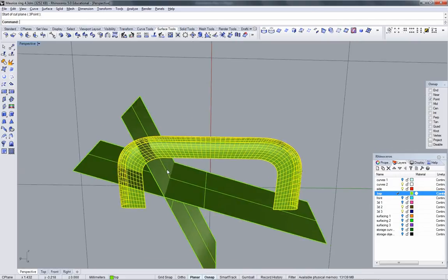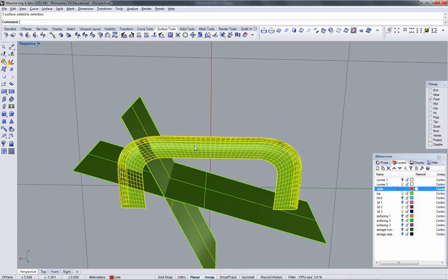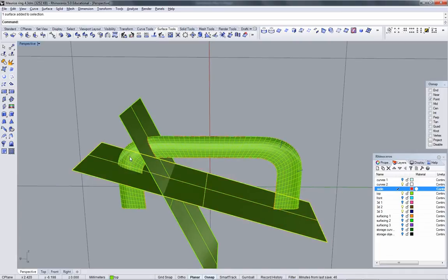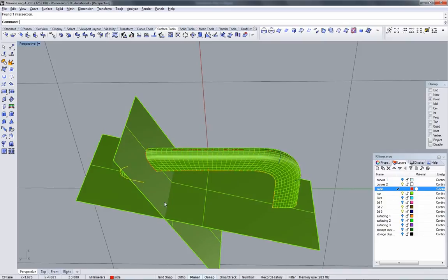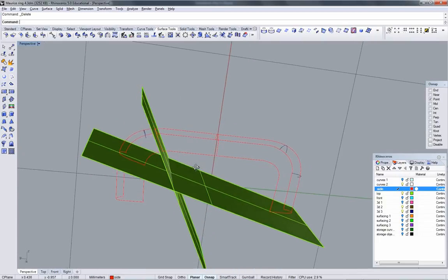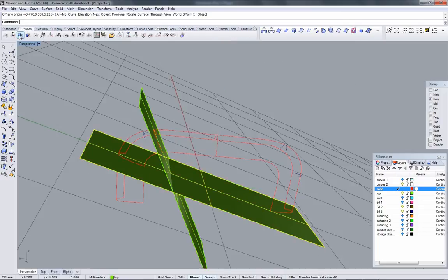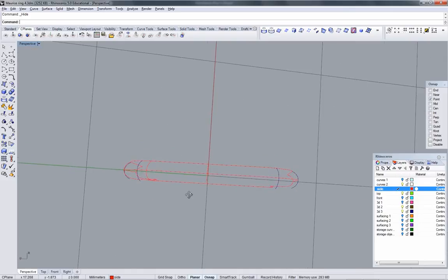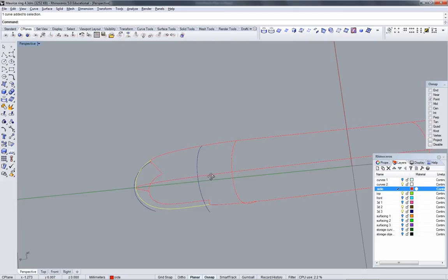Great. I'm going to get a cross section, intersection between these two. Going to get an intersection between those two. That should give me the cross sections. Delete this. And I will start with the lower cross section. So I'll put a C-plane to this. Hide both of those. Control H. Come in here and look at this, just to decide if I like it.